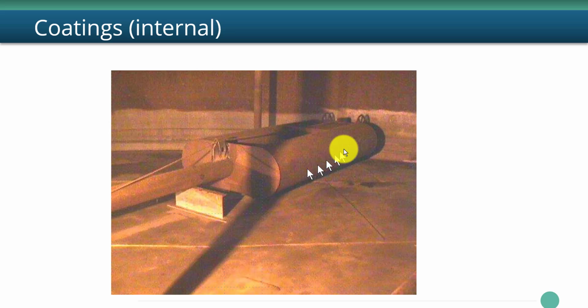Here is a pontoon used for a floating suction, and there's a different environment. Inside this pontoon is air, and so if you were to get a leak, the buoyancy of this pontoon would change, and there are many of these types of devices sitting at the bottoms of tanks because corrosion holes have penetrated through them. So this just illustrates one of the many environments that a tank is subject to in terms of corrosion.